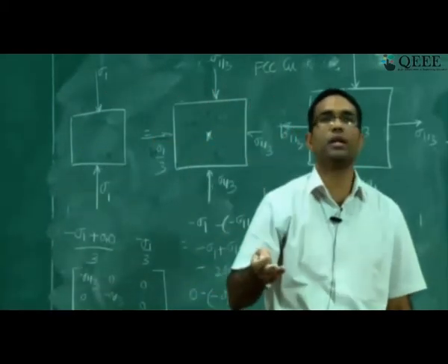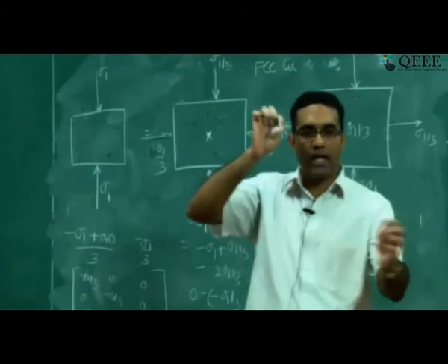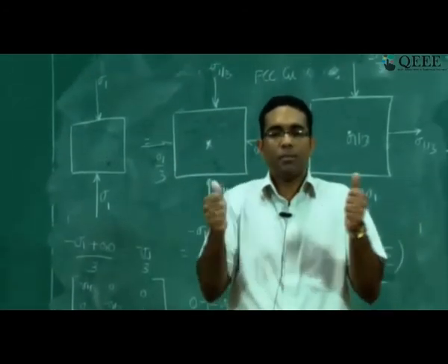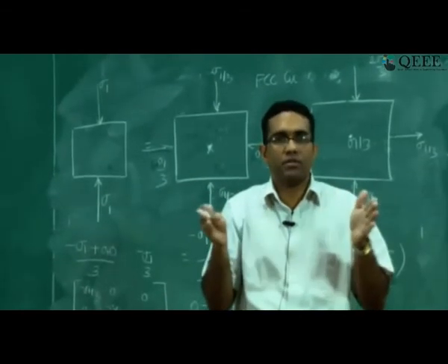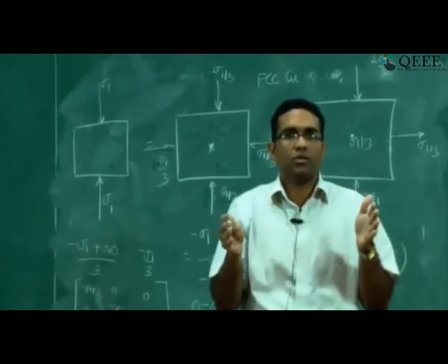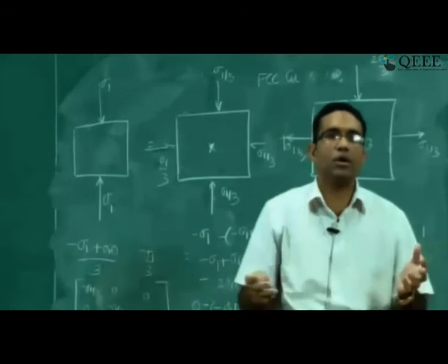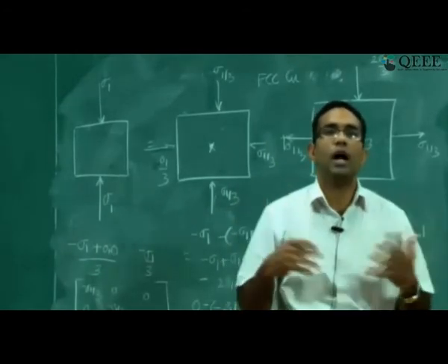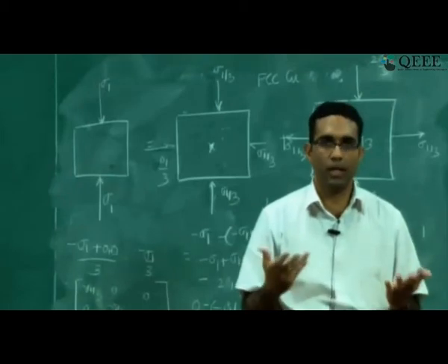It has cubic symmetry. When you pull it along the diagonals, it will strain by a different amount as opposed to when you pull it along the faces. So the ideal isotropic materials are amorphous materials which have no underlying structure associated with them.